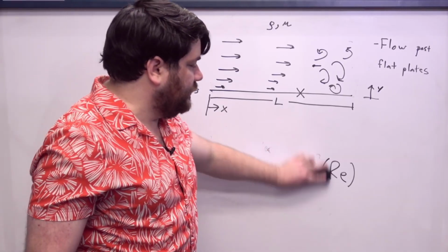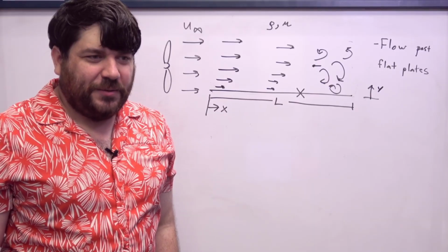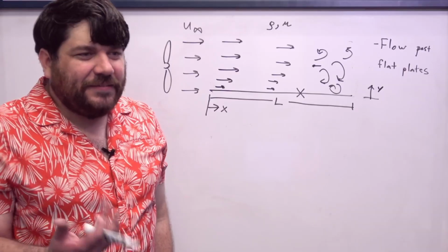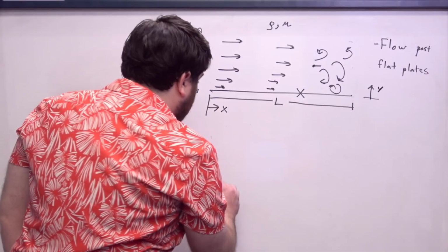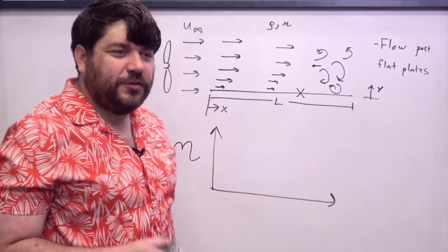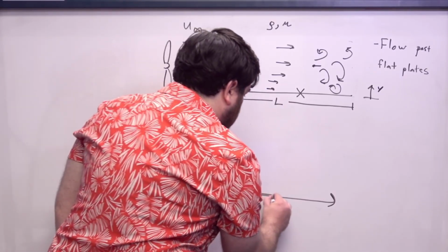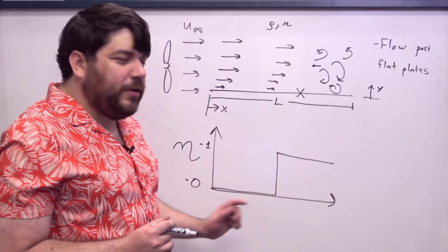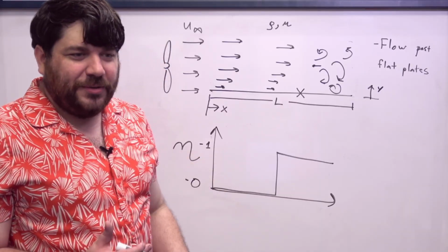And so the question is, if we know that the turbulence index is a function of the Reynolds number, what is that function, right? Technically speaking, that function is just a 0 to 1. We know that the value of the turbulence index switches from 0 to 1, indicating that for some Reynolds numbers turbulence doesn't occur, and for some other Reynolds numbers turbulence does occur.